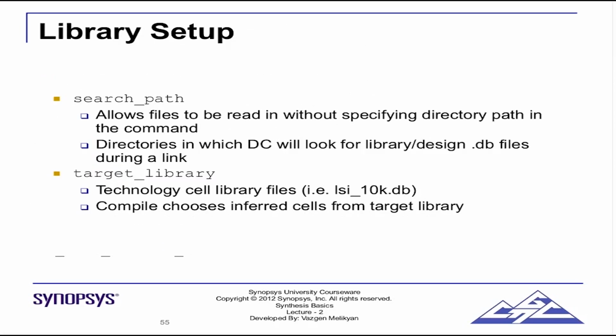Target library is the actual standard cell library which you want the tool to use to map your design and optimize your design. The compile process will choose inferred cells from the target library. This is a very important word, inferred. That means if you have written Verilog RTL code, you are telling the design compiler by the use of target library to use the standard cells in this library to implement my design.